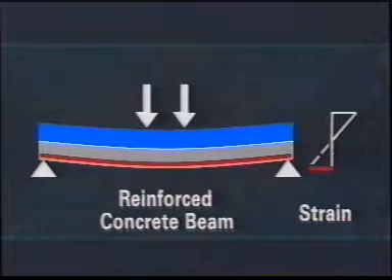In a reinforced concrete beam, it may be assumed that concrete has a negligible tensile strength, and that the reinforcing steel carries all the tensile stress in bending.